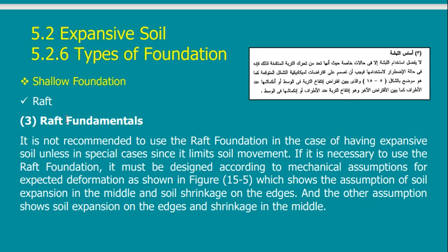The expansive soil will carry it up, and the structure will, at least in good condition, be lifted as one body. But in most cases it would tilt, it would crack, lots of problems. So if I want to use raft foundation for a special reason, then I should use raft foundation with openings, so that I help in relieving this stress.